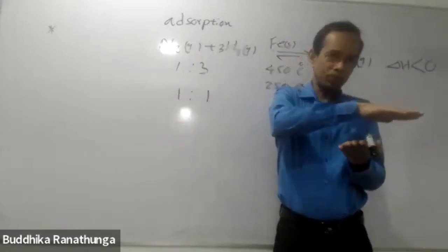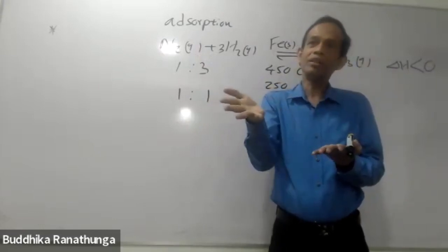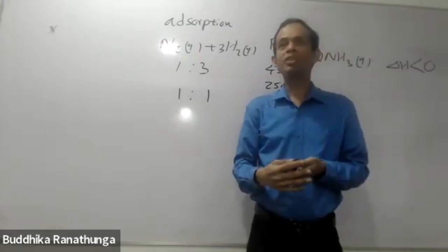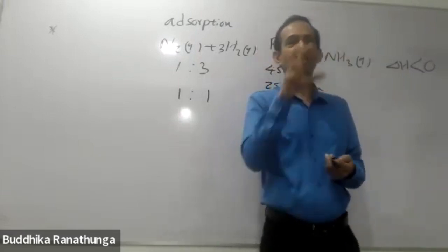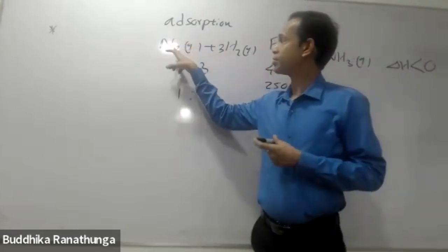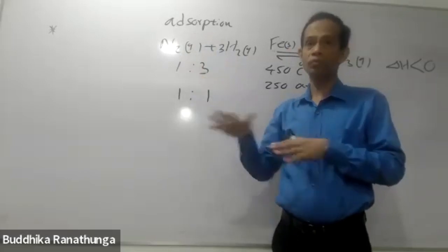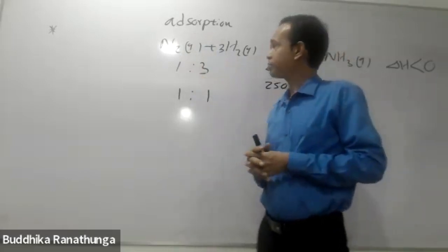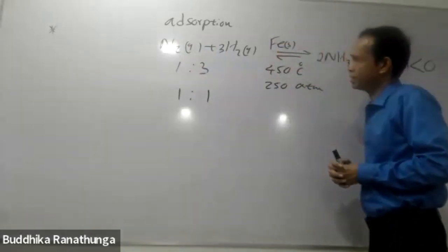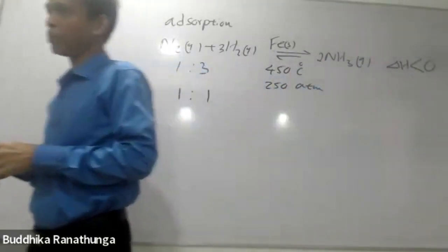If the surface of the catalyst is covered by dust, then adsorption is disturbed. Therefore, it's very important to use the reactant gases in a very clean form. Then the other very important point.